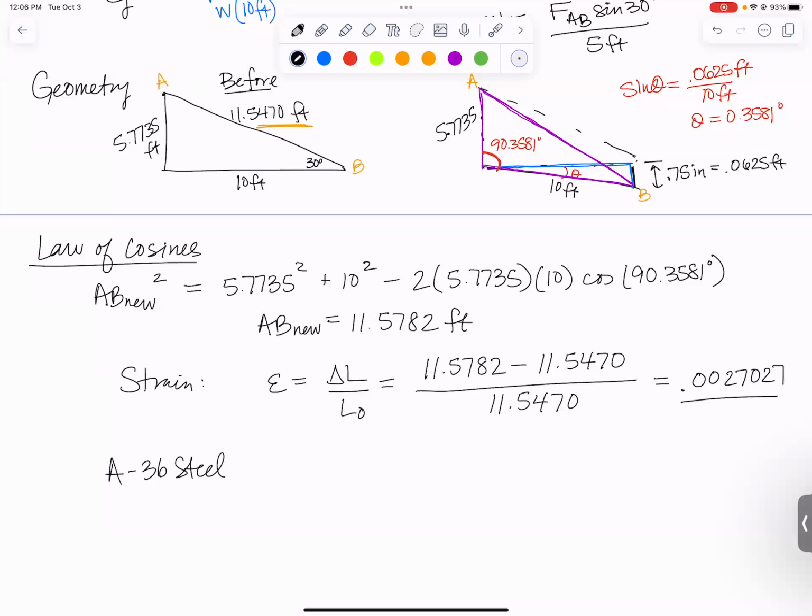And in the column for modulus of elasticity, it just says 29. Well, 29 what? Make sure you go look at the very top of that column. It says modulus of elasticity E in 10 to the 3rd KSI. So I need to write down times 10 to the 3rd KSI. So that's the value I get from the table in the back of the book.